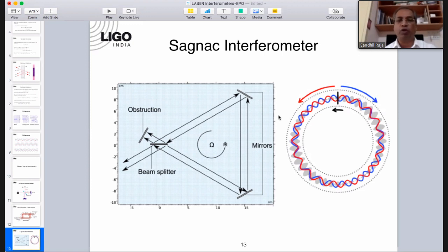It is named so because it exhibits the Sagnac effect, which says that if the interference pattern exists inside the Sagnac interferometer, and the physical interferometer is rotated, the interference pattern is stationary with respect to the stars. It's inertial, so it can be used to measure rotations to great accuracy. All optical and laser gyroscopes work on the Sagnac principle.